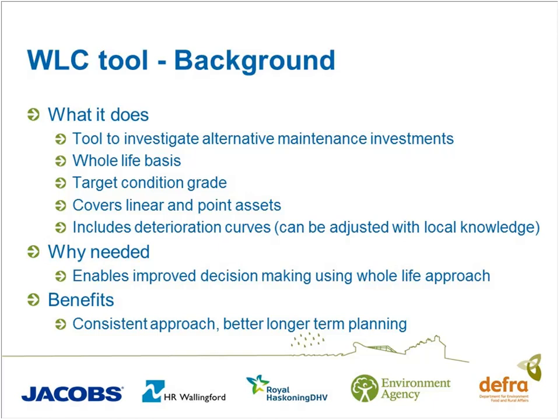and to do that, the tool incorporates a set of deterioration curves which we can adjust with local knowledge if we've got some information about the way those assets are deteriorating. We're using the tool because we want to improve decision making. We want to make sure we're making the right investments over the whole life, and I think it helps bring a consistent approach to long-term planning, and it's the sort of thing we need to do if we want to demonstrate an accredited approach to asset management, such as ISO 55000.